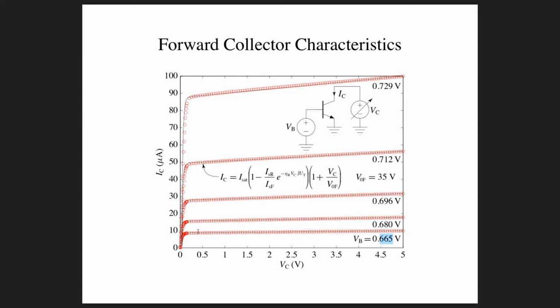And so in practice, we will subdivide the saturation region into what we might call soft saturation, where the transistor is formally in the saturation region, but is behaving in a manner that's very well described by the forward active model. And then we have so-called hard saturation or deep saturation, where we have something qualitatively different going on.